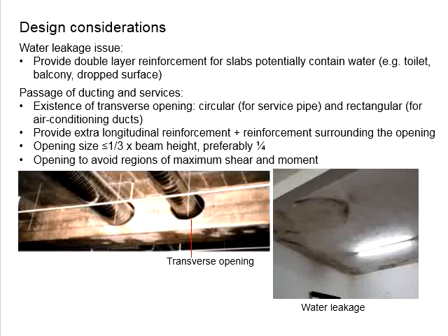You know that the circular section is still okay as it doesn't have orthogonal corners, but when you deal with a rectangular or square opening, this will be a bit harder, as stress can easily concentrate at the corners of the opening, and the member can easily be torn apart under loading.